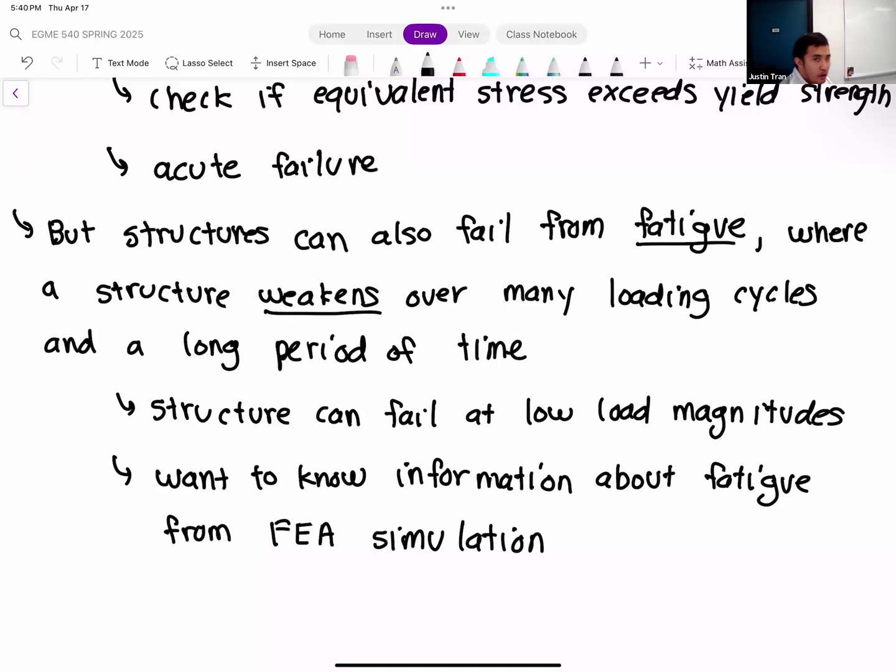All right, so there's a lot of motivations to solving for fatigue life analysis. Okay? There's one big problem of doing so with FEA. Now, when you run a computational simulation, and this is true for any computational tool, it's true for CFD, finite volume, finite difference, finite elements, right? Any computational tool excels at solving for things in the short term, right? So for the result after a couple of seconds, at most maybe like a minute of time.